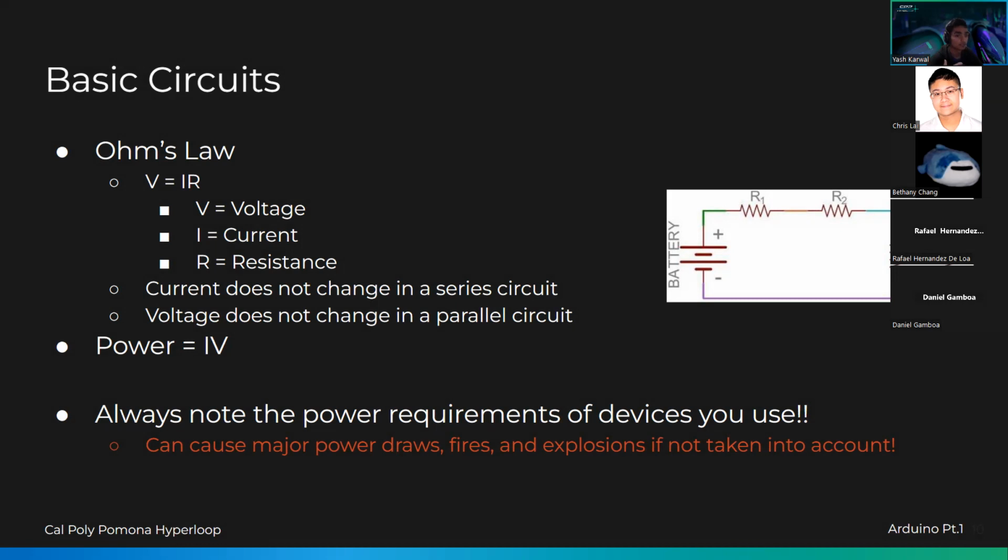And so right here, these two are in series and these two are in parallel. Current does not change over components in series. So these two resistors have the same current, but the voltages could differ. You can use V equals IR to find out, since there's different resistance here versus here, and the same current flowing from the battery, the voltages in this versus this.